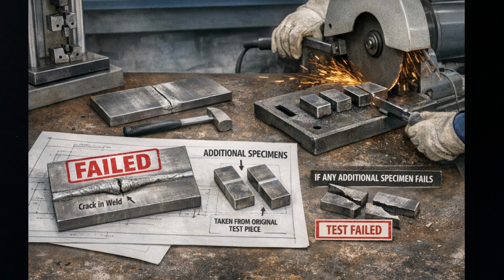Destructive test specimen failure. If any test specimen required by Table 1 or Table 2 fails to meet the applicable acceptance criteria, the test piece is considered failed. A new test piece with the same welding parameters may then be welded. However, before making a completely new test piece, there is a provision for taking additional specimens from the original test piece. If adequate material remains, 2 additional test specimens may be removed from the original test piece for each specimen that failed. The additional specimens must be taken as close as possible to the location of the original failed specimen. Each additional specimen is subjected to the same test as the one that failed.